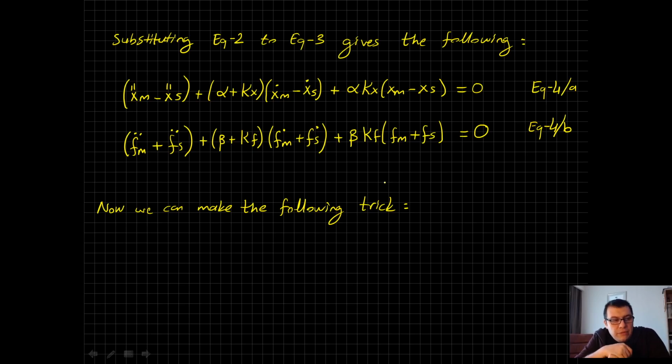And we have come to the point where we told that the force generated by the spring side of the environment is, in most of the applications, dominating the mass induced force and the damping induced force. That's why in the majority of the problems we can assume that a pure spring environment exists.